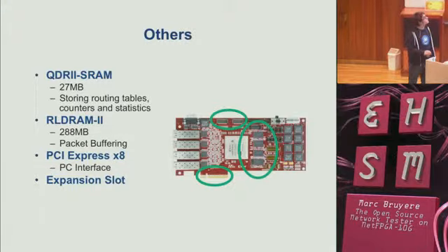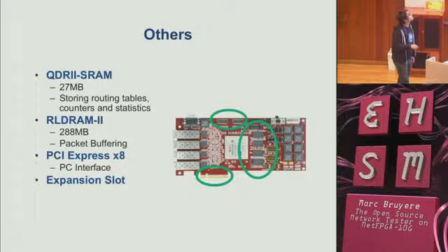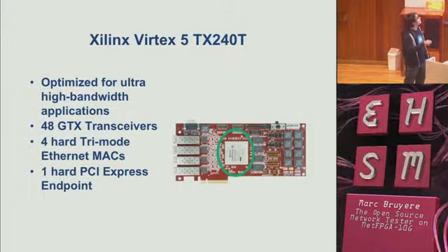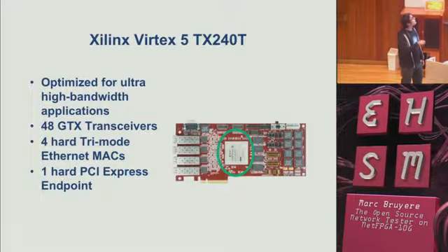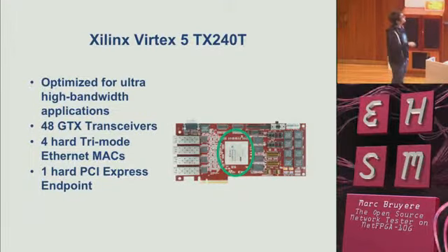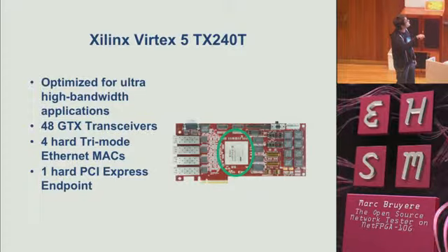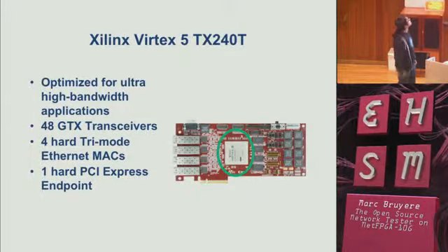And you have an extension slot that allows you to get the different GTX transceivers, to extend the connections of the FPGA itself, if you want to use different ports and connect channels in and out of the board without passing through the PCI.